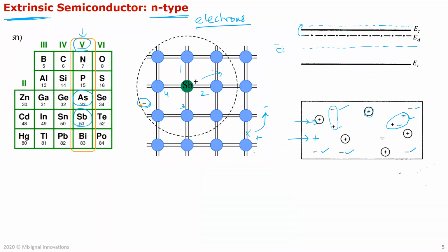So basically, in simple terms, if you want to make silicon more conductive, you dope it with some group 5 element, which has 5 valence electrons. So when you dope it, there are enough arsenic or antimony atoms per cubic meter of volume inside the silicon, such that it gives you enough free electrons per unit volume for you to conduct. If you want it to be heavily conductive, you dope it really high.